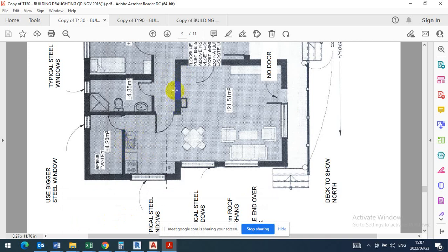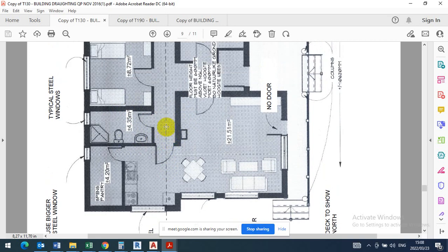When you see it's thick, it means the roof maybe on the sitting room is heavy, so they are using the external wall size. So this will be 220, this will be 220, this can be 110. They are thinner, but the way it's supposed to be, all internal bricks must be 110. But I'm going to work with 220 here. It's very thick. Okay? And the passage is not usually given to you.